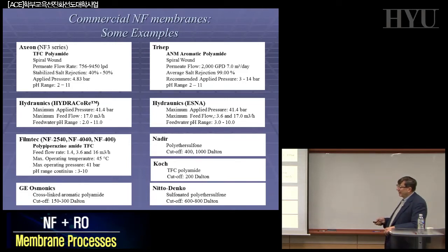In this case, you can have a cutoff of the order of 400. Remember, sodium chloride is 58 Dalton. This is 400 Dalton. That means it can be an amino acid or a lot of pharmaceuticals. Sodium chloride, potassium chloride, lithium chloride, salts are going across, so you can remove them easily and concentrate the components of interest.